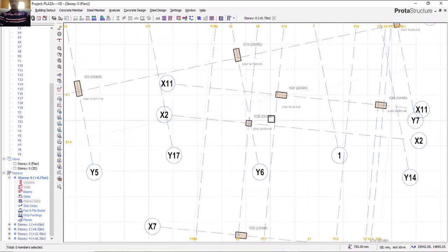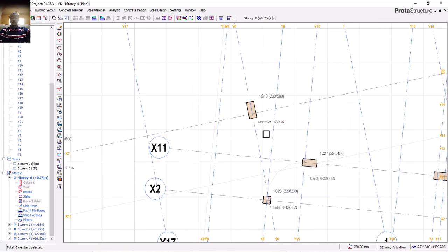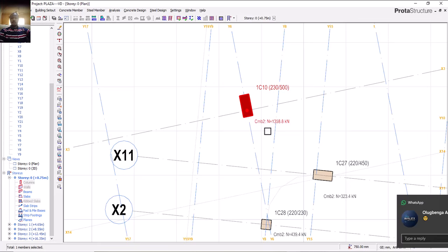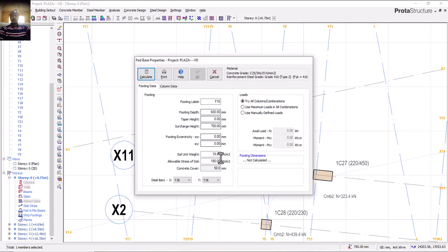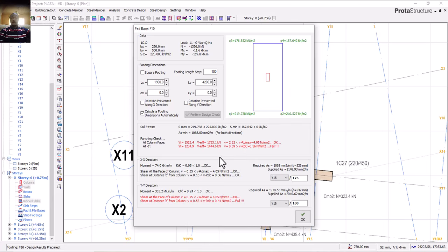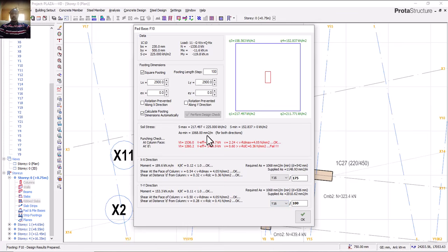All right, let's go to another one, because I have to consider those ones that are high somehow. So let's see other ones. It's this area that should be high. Okay, if I click on this one, 1000 plus, I'll right click and click on insert pad footing. Let's see, we are still using 600. Can you see also square? This one minimum, which is 100, is still okay. It's not less than 100. This one is also okay, but if you look at punching, it's still failing.